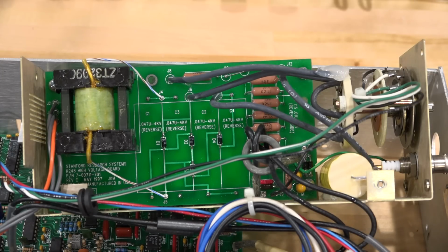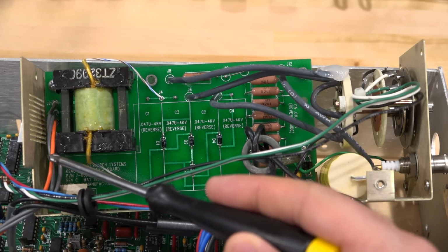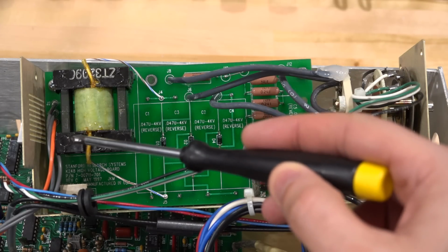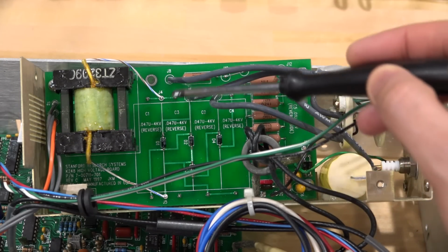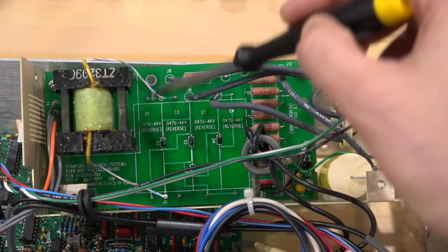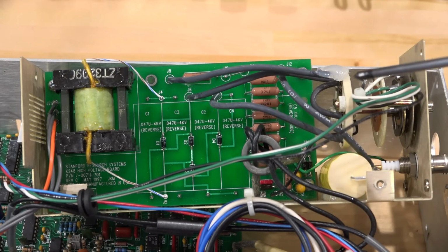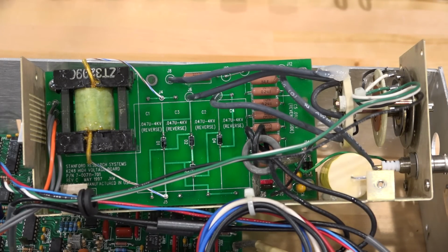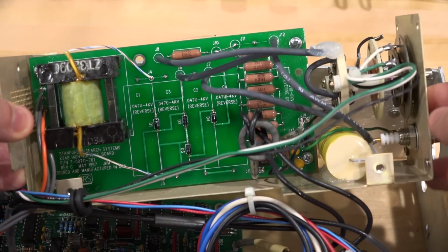And here's a close look at the high voltage portion of this 5000 volt power supply. It has a cover. I've taken everything off so we can just quickly take a look at it. The inverter input comes over here, driving the primary side of the transformer, and the two outputs that go out over here go through the voltage quadrupler. So the voltage at this point is 1/4 of the voltage that will be developed at DC at the output. Basically, the AC to DC conversion also achieves the quadrupling of the peak voltage value.